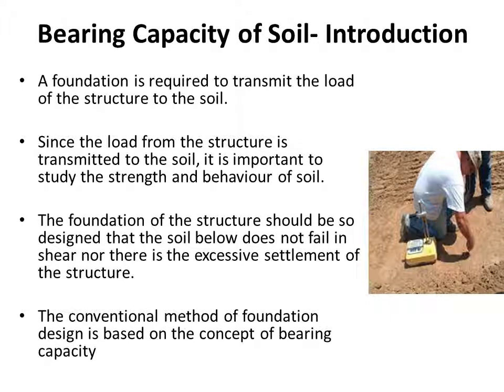Bearing capacity of soil. As we all know, a foundation is required to transmit the load of the structure to the soil. Since the load from the structure is transmitted to the soil, it is important to study the strength and behavior of the soil. The foundation of the structure should be so designed that the soil below does not fail in shear, nor is there excessive settlement of the structure. The conventional method of foundation design is based on the concept of bearing capacity.